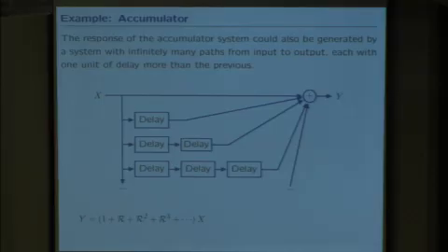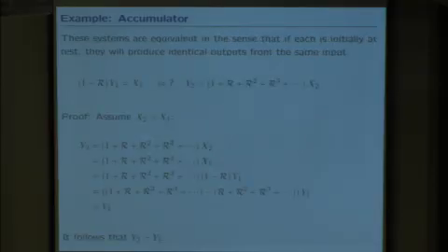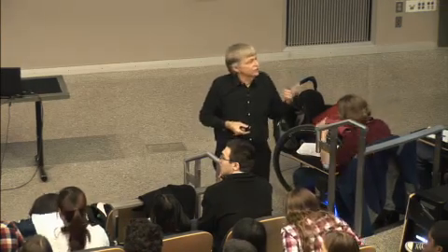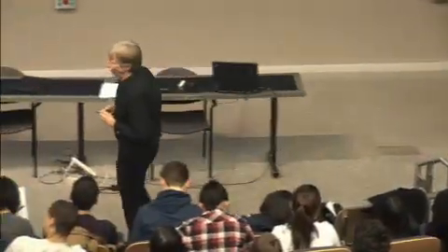There's something similar about the simple feedback system, which can be represented by that operator representation, and the infinite feed-forward system. This is a simple feedback system. This is an infinite feed-forward system. There's something the same about those two. In fact, they're equivalent in the sense that if all the delays start out with initial conditions of 0, they will generate the same response to all possible input signals.